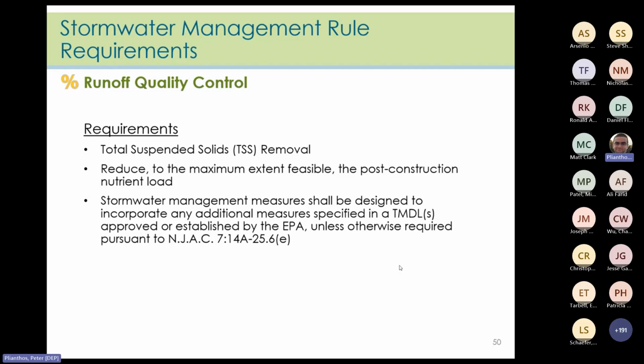When the water quality standards are triggered, stormwater management measures for water quality control are required. Why is that? Developed sites typically do not have the surface roughness to slow down runoff. This means there generally is not enough time for any pollutants to settle out, resulting in direct discharge to water bodies.